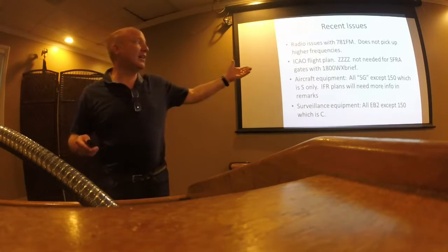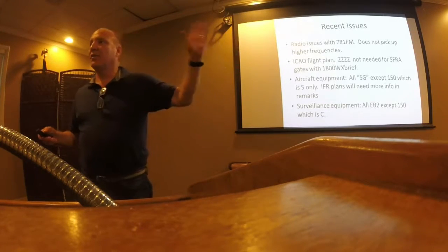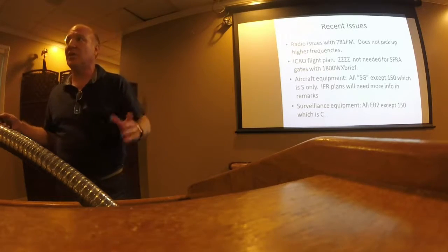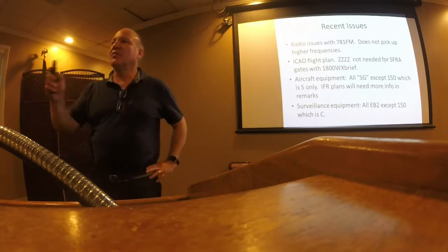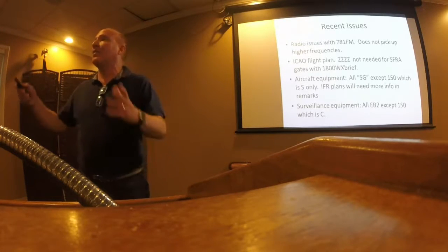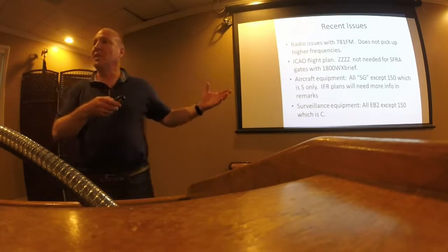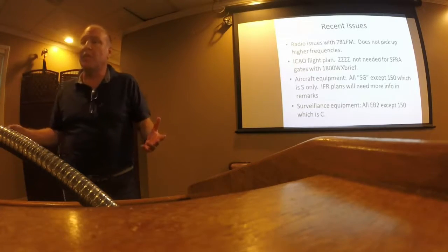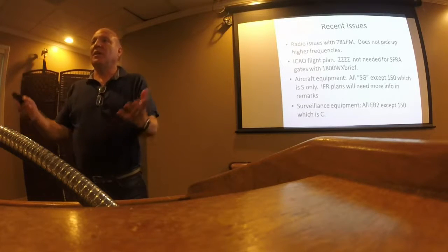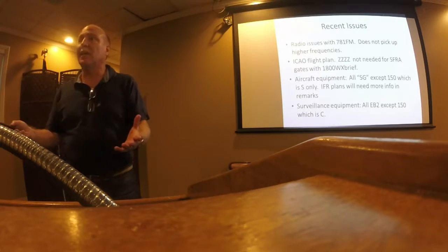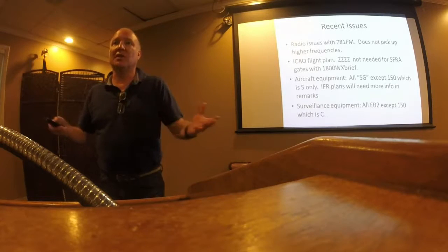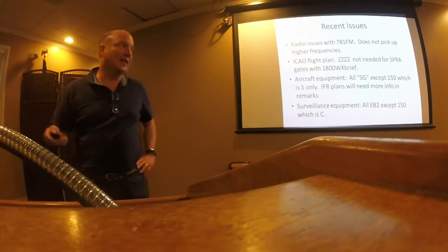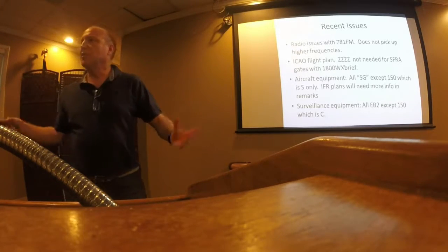I have been filing with Sierra Golf for all my VFR flights in the 1-800-WX brief without any issues. I think the problem is if you're filing an IFR flight plan, you'll have to get some more stuff in there for them to know what you're using in the plane. But for VFR, from a practical standpoint, they shouldn't care, because you're not going to be using approaches, departure procedures or arrivals. But it is a work in progress.